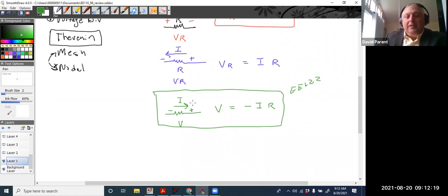And so what do I remember from 98? It doesn't matter how you assign it, as long as you're consistent, you'll always get the right answer. But the thing is, it's probably better to always draw it the right way, or a way that makes physical sense, because if you're drawing an arrow one way but forgetting the voltage drop goes the other way, this is mathematically correct, but it's a little counterintuitive. So you might get the answer wrong. So it's really important to always put the current directions and the voltage drops across the resistance in the proper direction, if you can.